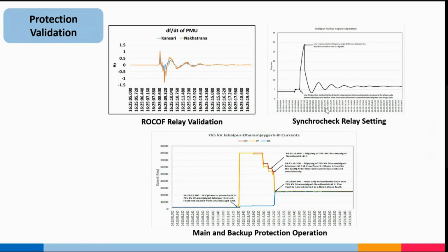And subsequent to that, for other kinds of protection, which are slightly delayed in nature, like directional earth fault, which has certain limitations in that it will operate after a certain point of time. So this is a delayed kind of thing, it is not generally instantaneous in nature. In that case, you will be able to monitor those responses, whether they are validated or not.